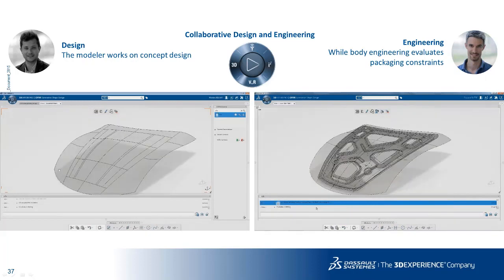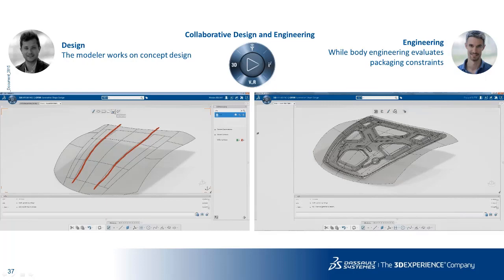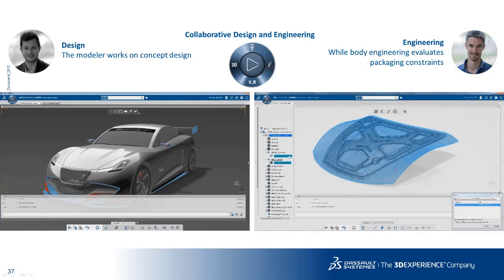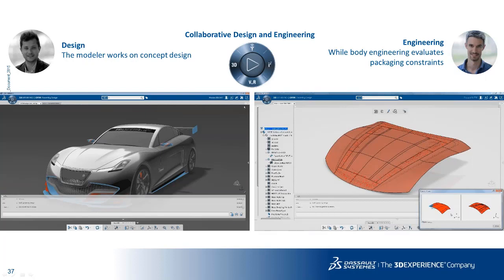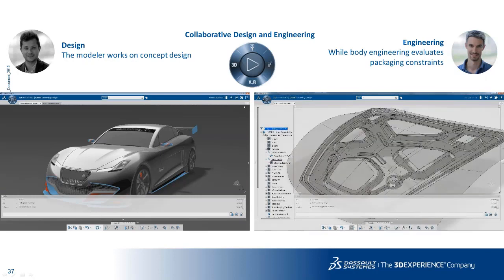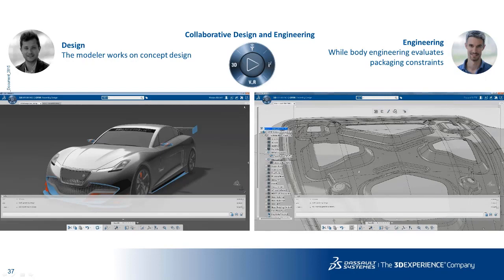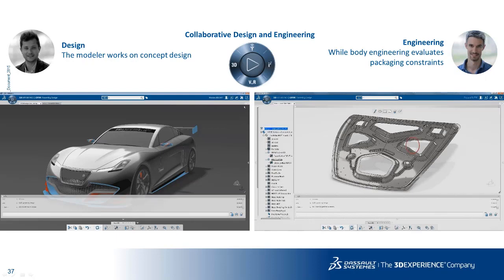What he's going to do right now, the structure is referencing the initial hood, and we've added this packaging requirement because there's a larger engine option. So we need to put a power dome in this hood, and what you're going to see is the structure update as we replace the initial hood with the new one, and the engineer is going to update his part. I don't know if you can see it in the structure, but you can see how it accommodated the Change Studio surface proposal. And so this can change a lot.